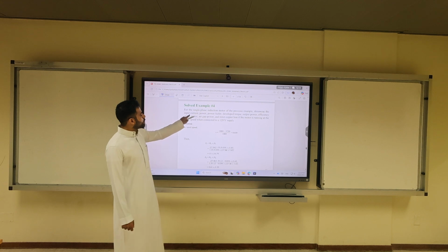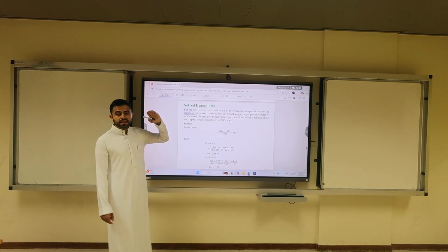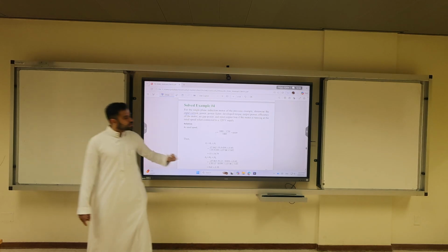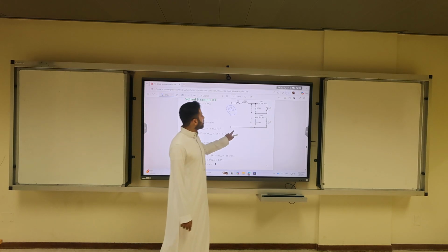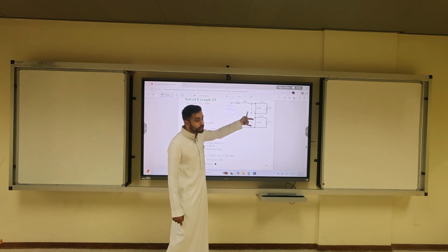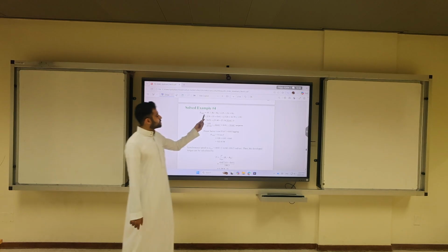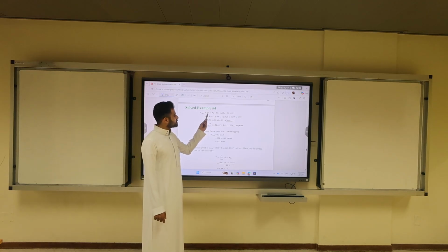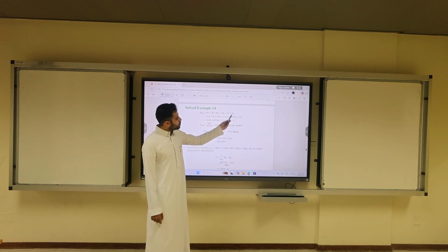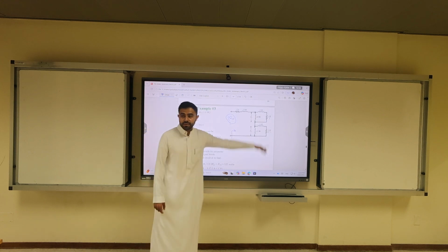Then after you find the forward and backward, what you have to find is the input current. This is the first quantity, the input current. Finding the input current is nothing but the input voltage over the equivalent impedance, which is this resistance plus the forward plus this impedance plus this impedance. Okay? Here, that's why we do it here. It's the forward plus backward plus R1, forward plus the backward plus X1. Add everything else. Can you do this using your calculator quickly?